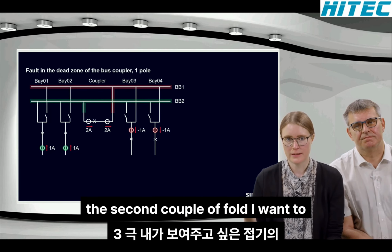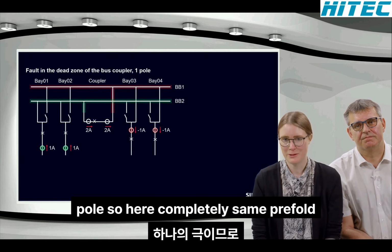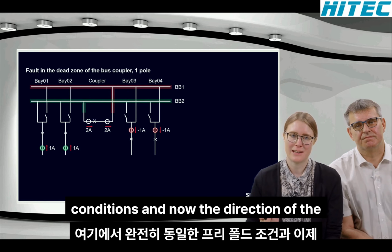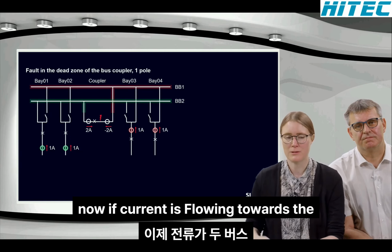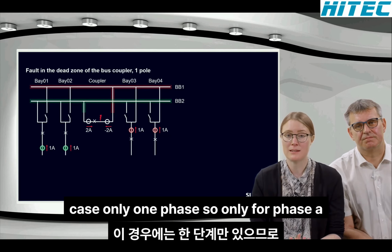The second coupler fault I want to demonstrate is almost the same, but 1-pole. So here, completely the same pre-fault conditions. And now the direction of the current in bay 3 and 4 and in the right coupler CT changes. And now current is flowing towards the fault from both busbars, but in this case, only one phase. So only for phase A.